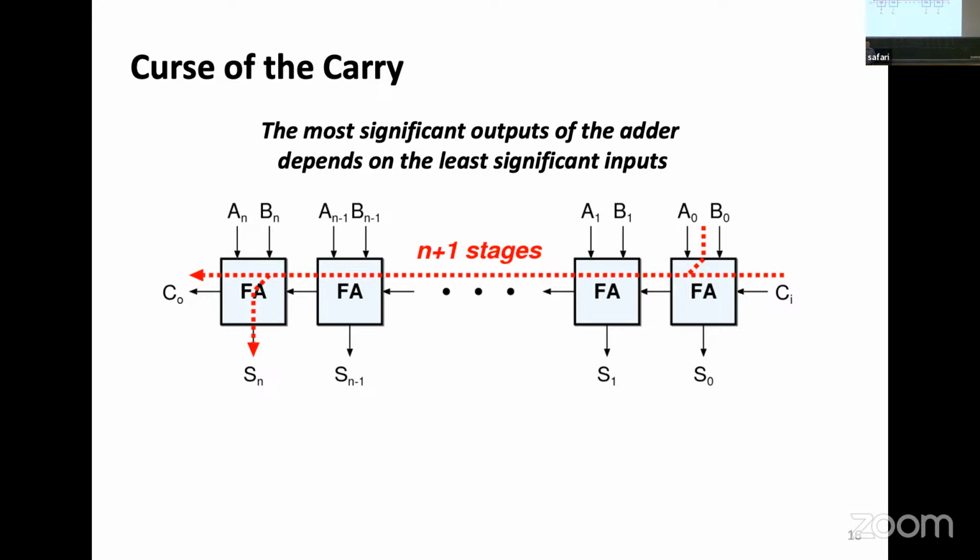Do you know why they call this thing a ripple carry adder? Because the carry ripples through, and in the worst case, it takes as many steps as the length of this calculation to get the output result correctly. Now, going back to the combinational logic and timing we were talking about, the first time the output changes is when this input created a result of 0, 1, 1, 1, 1, 1, 1, 1, 1. That was our contamination delay.